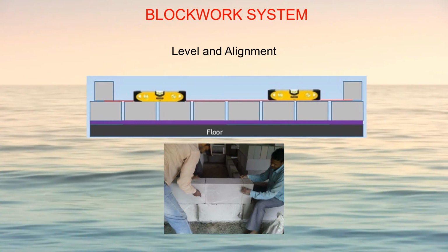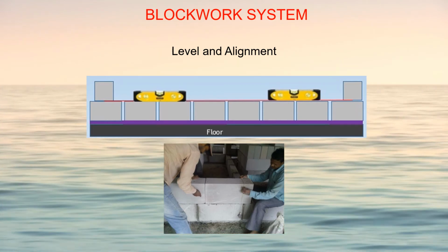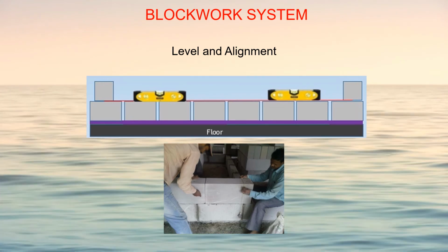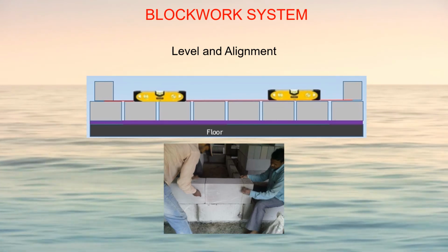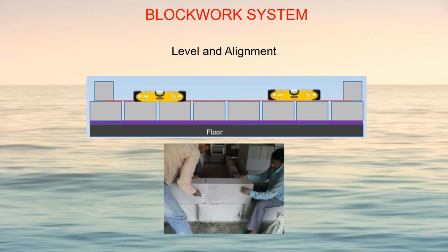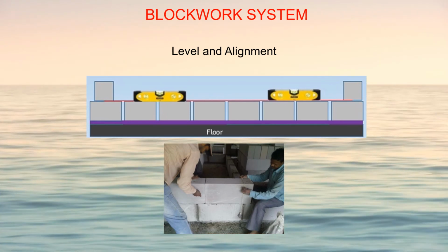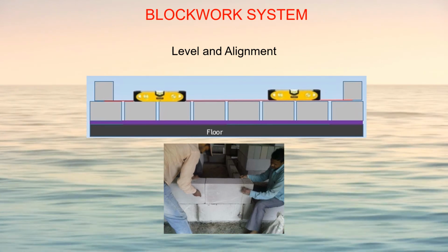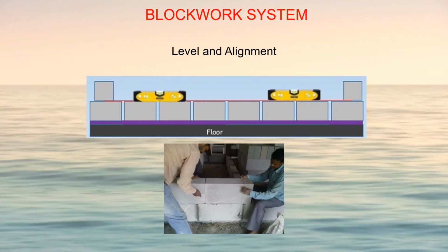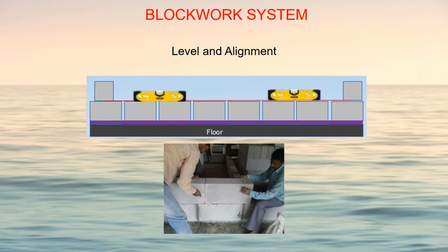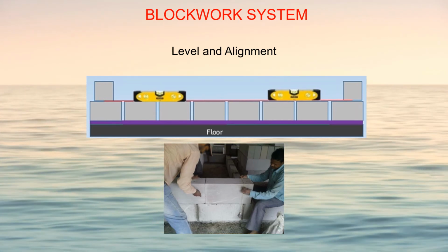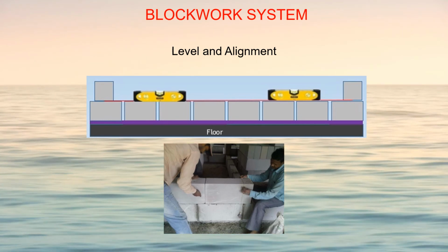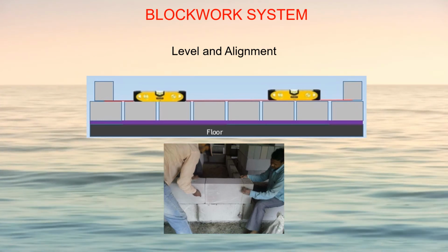Each fixed block should be checked for its line, level, and plumb. Lay mortar for full bed width and for a length of 3 blocks at a time. Lay 1 block at a time, gently pressing it in the mortar bed. Use a 12 mm thick plywood piece to ensure uniform vertical joints. Excess mortar coming out on the edge while pressing the block in position in the bed mortar is to be taken by trowel